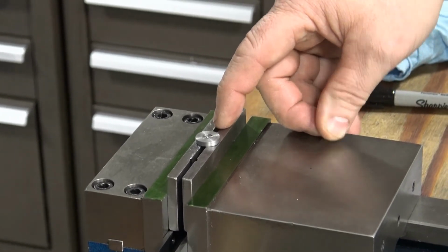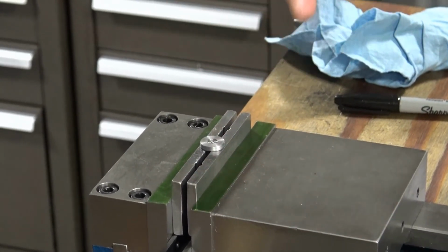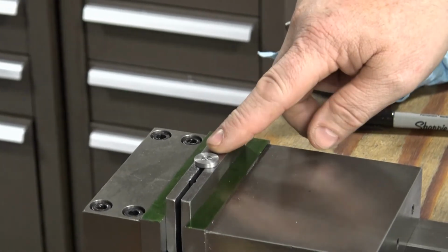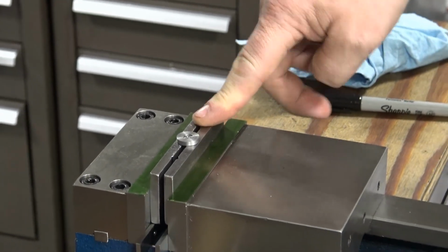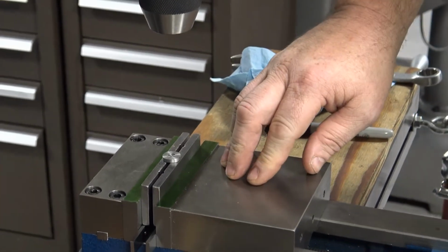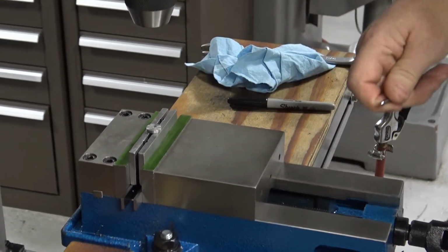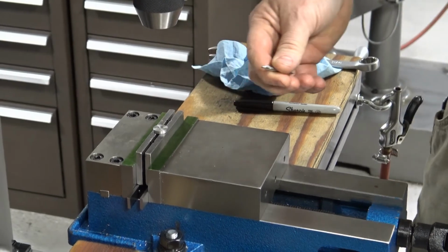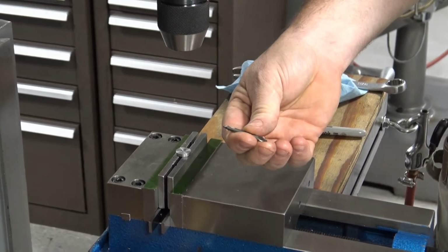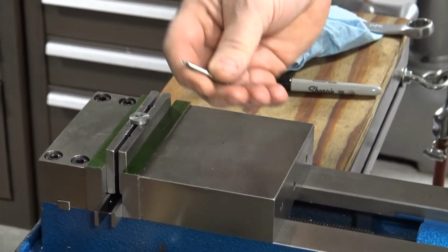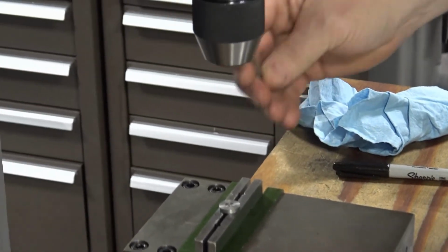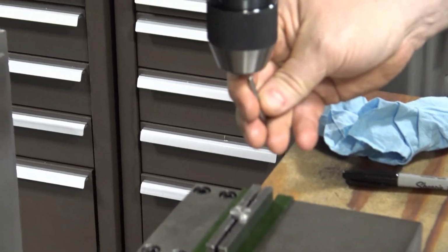What we care about is that there's enough room that when I drill and ream down through, I'm not cutting on those plates. Some of the plates do have some machine marks in it, but typically that's from a student that has made an error. So now that we have it clamped into position, here's our number 2 center drill again. I'd like to put that up in my drill chuck.